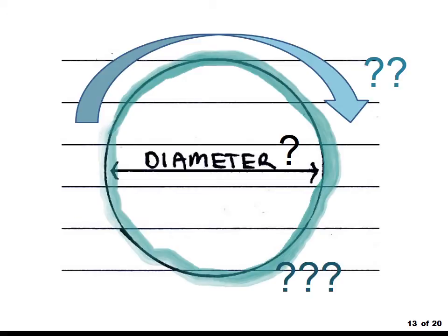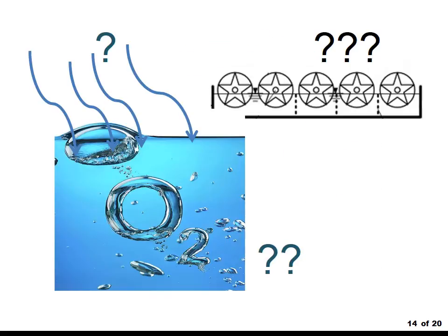Having this kind of data, we go further and start to think about the mass transfer coefficient, how much oxygen we're going to have in the system, and based on this data, how many RBC units we need in our system.